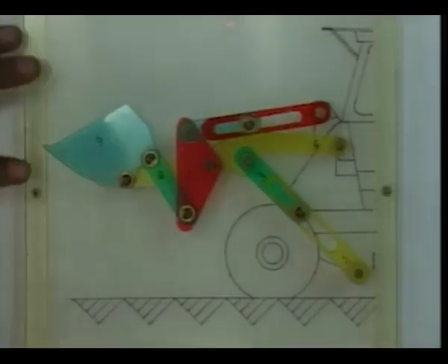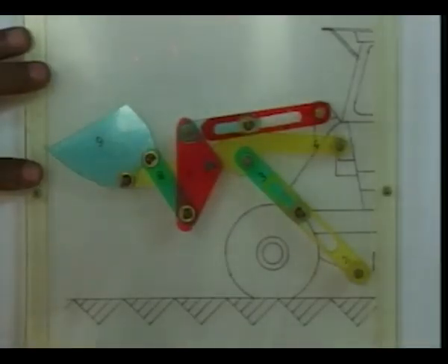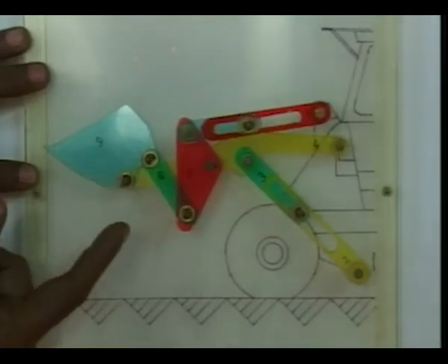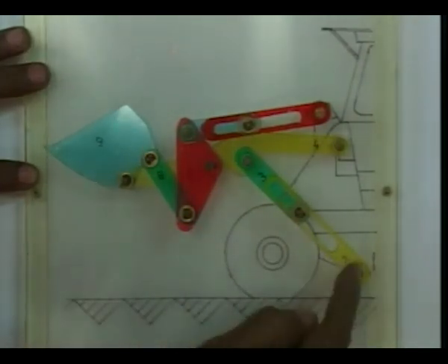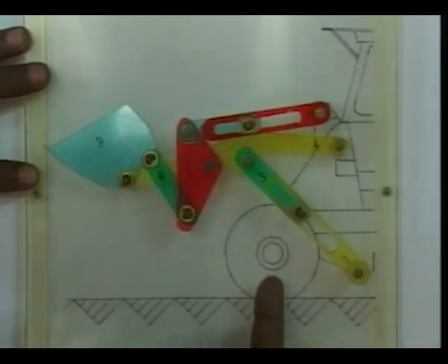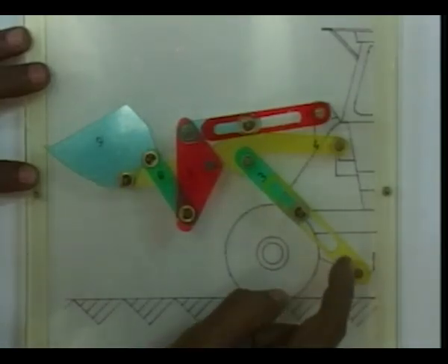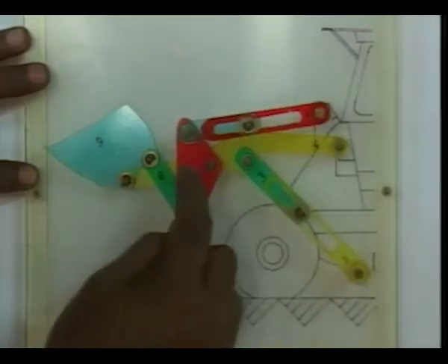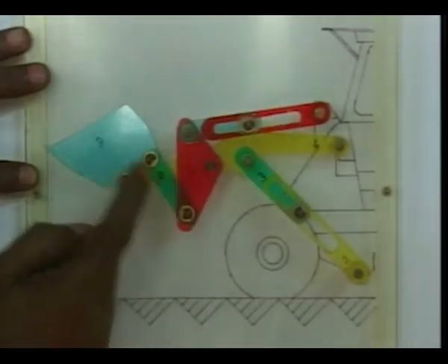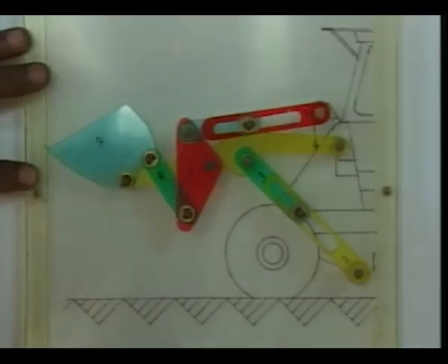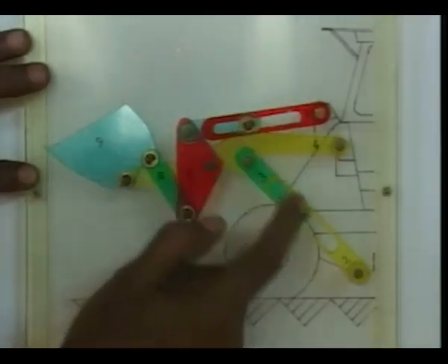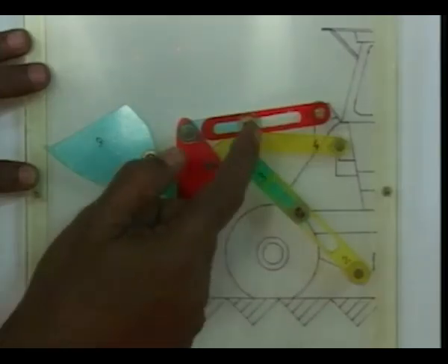As an example of a 2 degree of freedom mechanism, let us look at this model of a front end loader. This mechanism has 8 moving links and the fixed link is again the body of the machine. If I call the body of the machine, the fixed link, the first link, this is the second link, this is the third link, 4th, 5th, 6th, 7th, 8th and 9th. This output bin is link number 9. Here we have 2 independent inputs provided by these 2 hydraulic actuators.